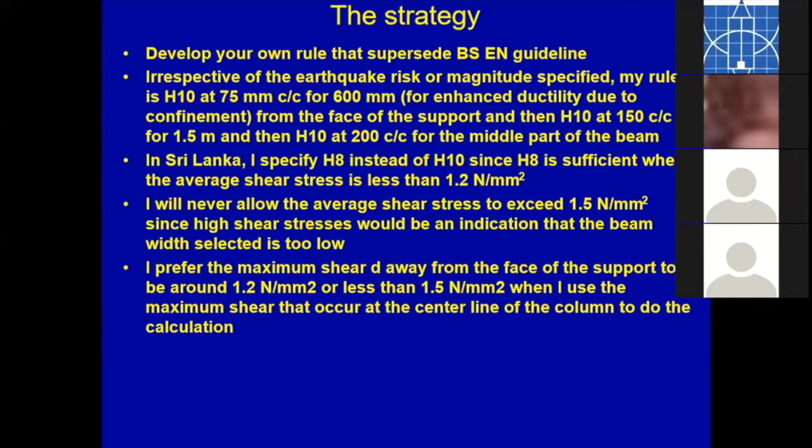You might think, okay, because we are using Eurocode, we can use high strength materials. If we can tighten the site supervision to the level that we use 50 megapascal concrete instead of 30 megapascal concrete, we can make many sections smaller, and that way we can save money. On the other hand, rather than reinforced concrete, you might consider using pre-stressed concrete. So the list can go on and on. But whenever you get a building, don't think it has to be reinforced concrete. It can be out of any material, especially the floor systems.